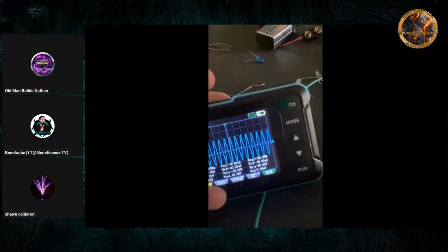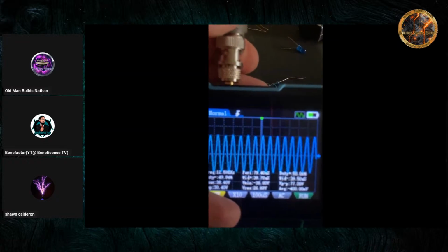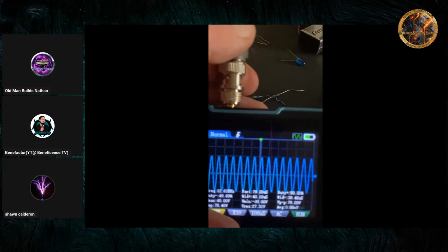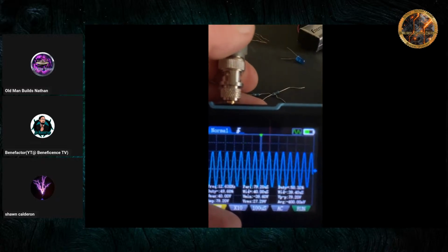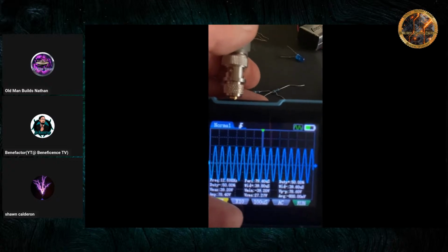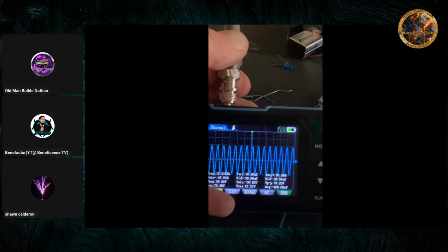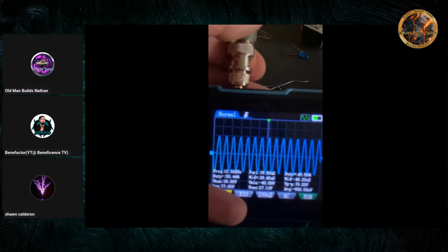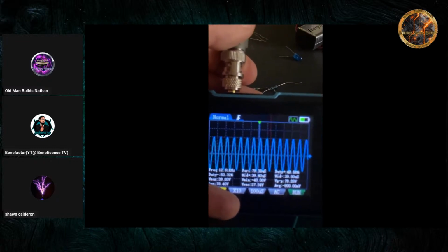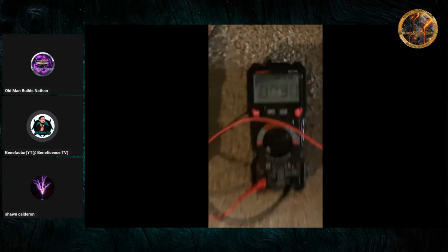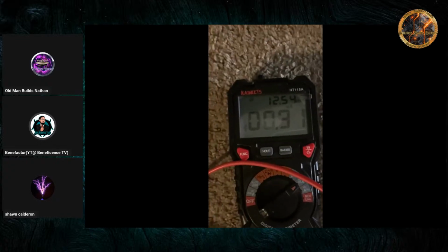Let's adjust the probe. Yeah, look at that. It's either exactly the same voltage or slightly less. The duty cycle did not skip a beat. Nice. So I think these are some significant results right here. See, in a minute, I hook up the load and get the correct current.